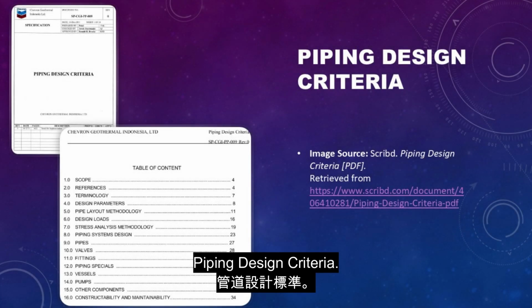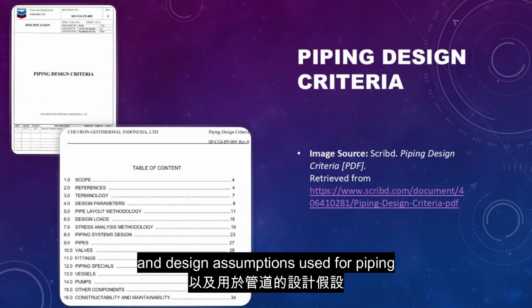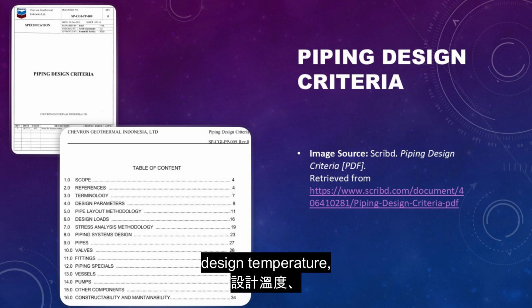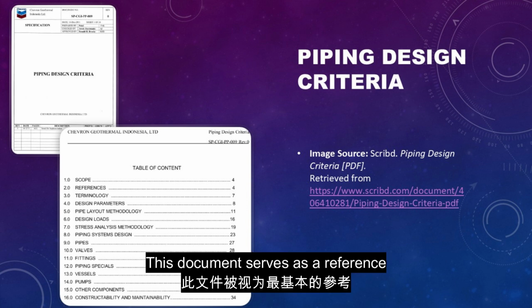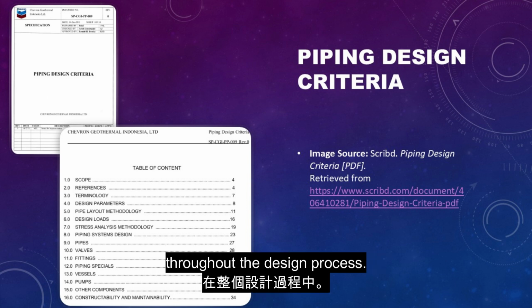Piping design criteria. The piping design criteria is a key document that outlines the fundamental rules and design assumptions used for piping layout and stress analysis. It typically includes parameters such as design temperature, pressure classes, insulation requirements, pipe spacing philosophy, flexibility and support strategy, and any special project constraints. This document serves as a reference baseline for all piping deliverables, ensuring consistency and alignment throughout the design process.